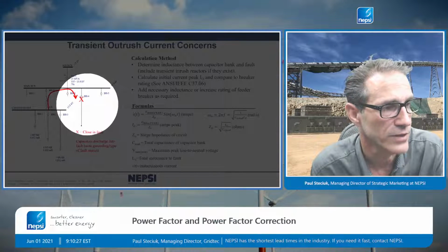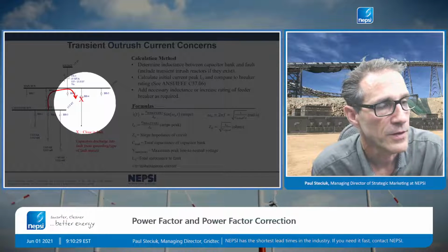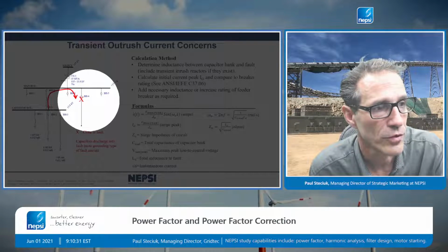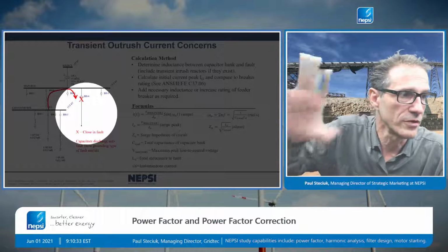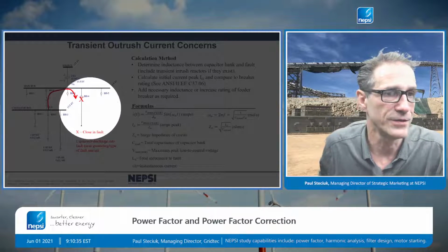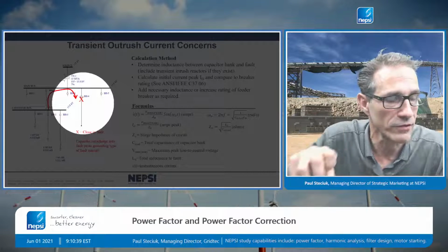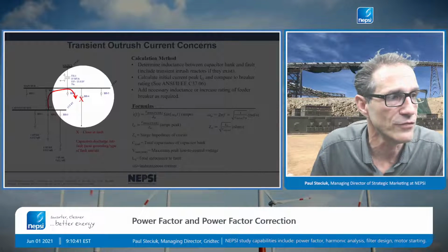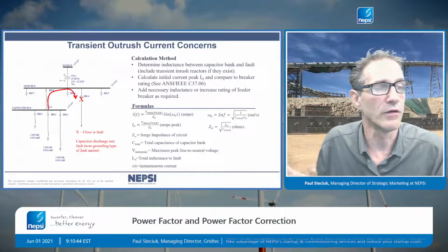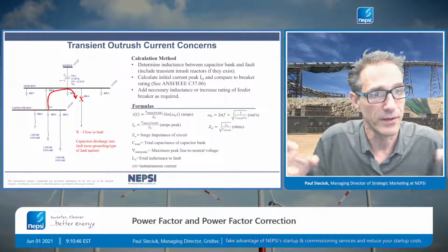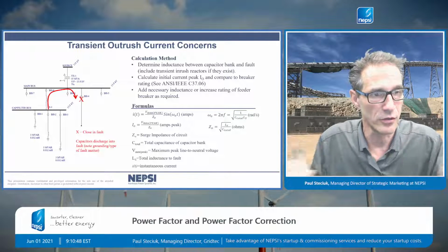You see the X under BH4. What happens is, if I have a permanent fault, say I have a cable leaving the substation, and a shovel digs into it and creates a fault in that cable, a permanent fault. The first thing that happens with BH4 is it opens, which then allows that capacitor bank to charge again and to go into operation.